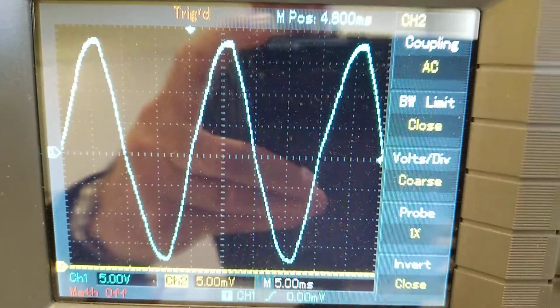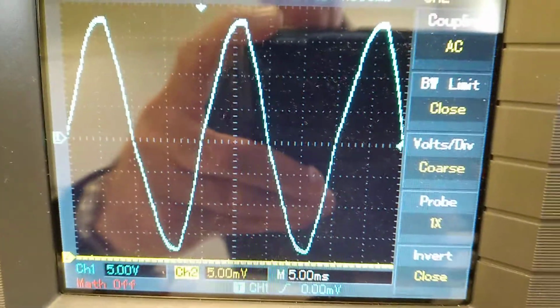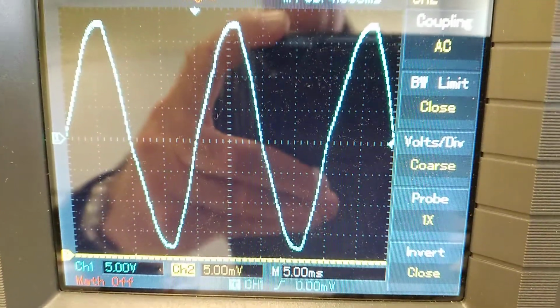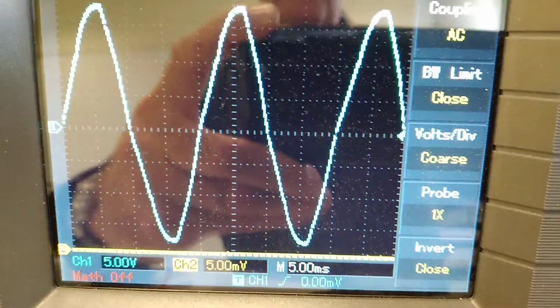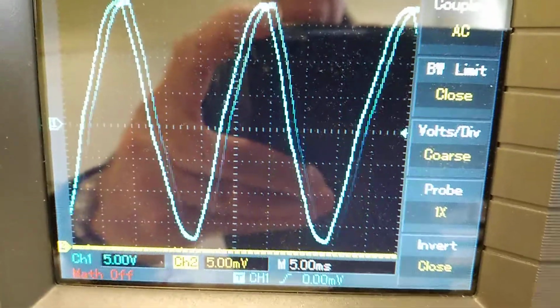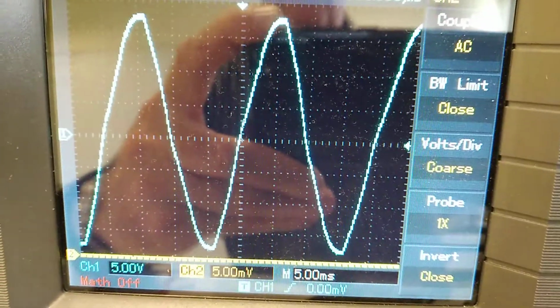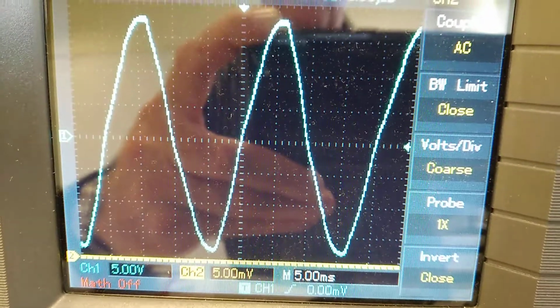Okay, now let's look at the frequency. So the frequency on 50 cycles here in New Zealand, the period should be 20 milliseconds on 50 Hertz. So let's just bring it back here to start my cycle at 0, just on the crossover of my X and Y axes.